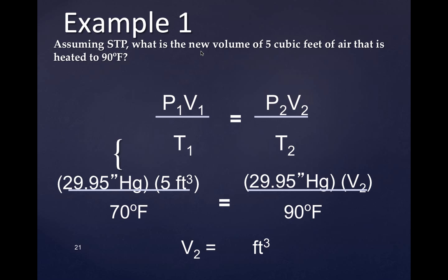Pressure and volume: you know that if you double the pressure, what happens to the volume? It goes down, right? It's half the volume. Twice the pressure, half the volume. Okay, now keep in mind that that's absolute pressures. Same thing with temperatures. Temperature goes up, volume goes up. Temperature goes up, you keep the volume the same, the pressure goes up, right? So there's our relationship there.